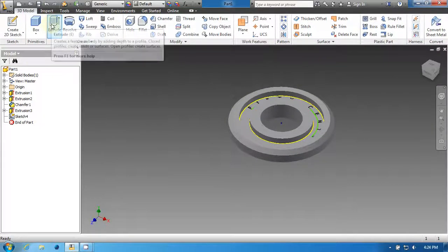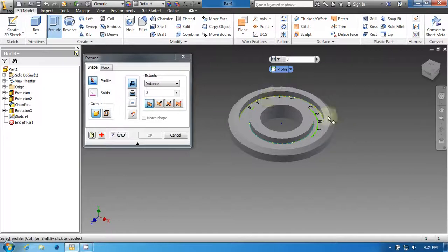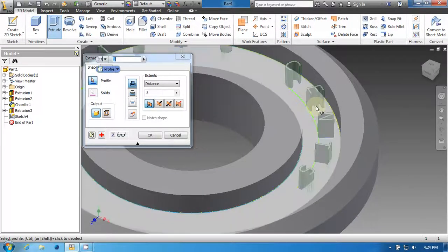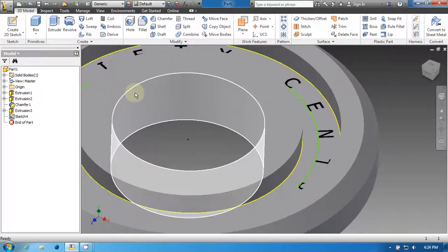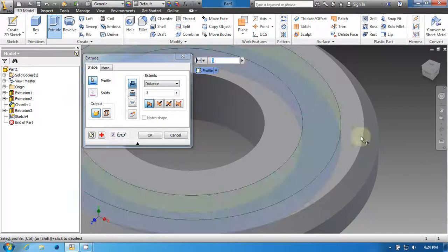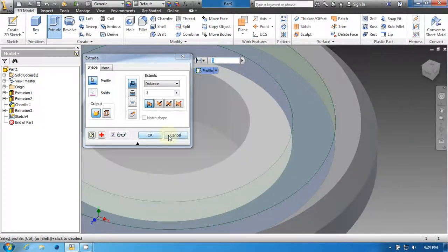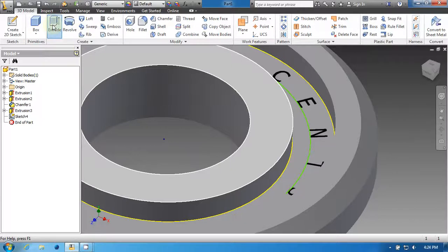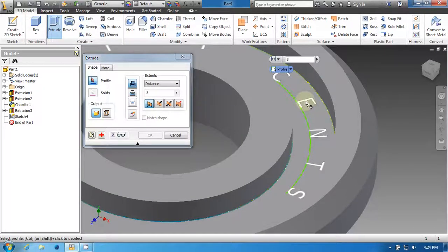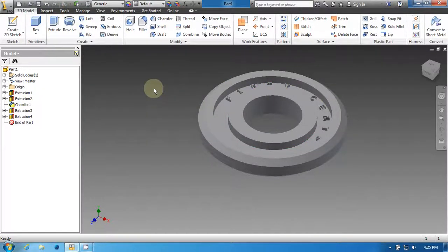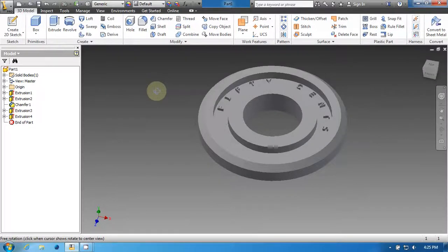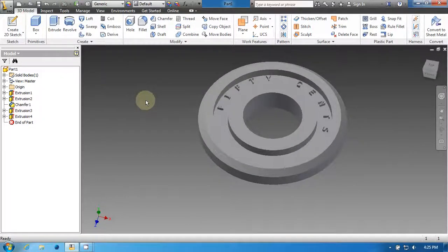This time click Extrude. And let's zoom in carefully and select the text. If you do it wrong, this is what will happen. You'll get this, which looks like nothing. So make sure you click Extrude and you pick the actual text itself. It should turn white. I'm going to get that to pop up about 2 millimeters. And how about 1? Okay. There you go. Starting to get a coin. This is the basics. Now from here, I'll show you some more advanced videos next.